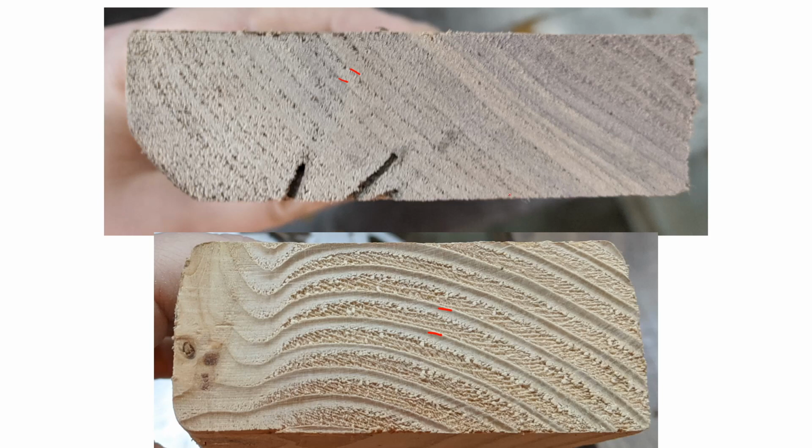So let's think about this though. We know that hardwoods will in general tend to be stronger than softwoods. So which do you think we use in construction and structural contexts? Now, you might think that we would use hardwoods. After all, more strength is better, right? For the same cross-sectional area, in a square inch of cross-section, as a general rule, we're going to get more strength out of hardwoods than we will out of softwoods.